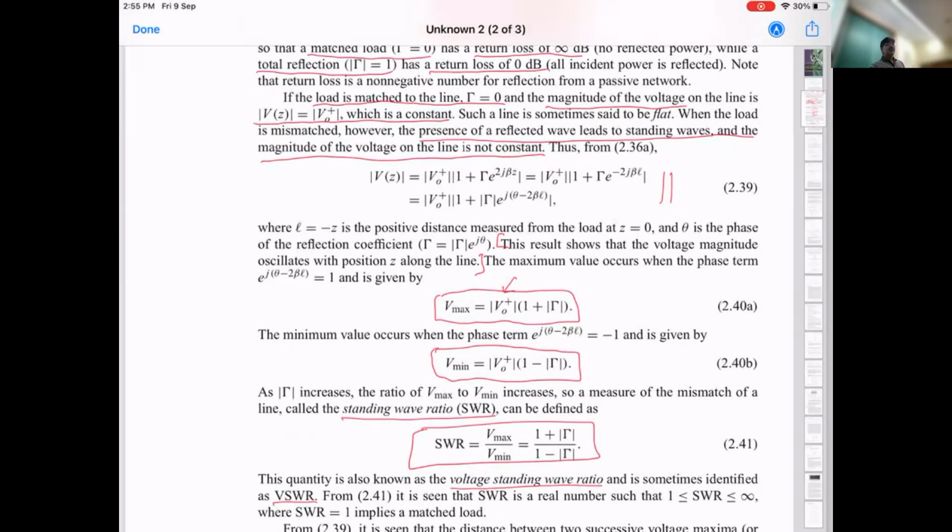When you look up the data sheet of a particular device, say one of the things you buy is a 50 ohm resistor, which is called a 50 ohm matched load, it is never exactly 50 ohms, and also the enclosure and all of those things affect the reflection of how the power couples to that resistor. Then you might find that it is given a specification either in terms of return loss or in terms of VSWR. The two are interchangeable because they both only depend on gamma.